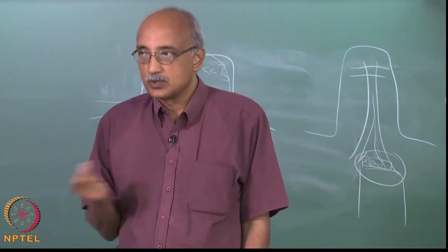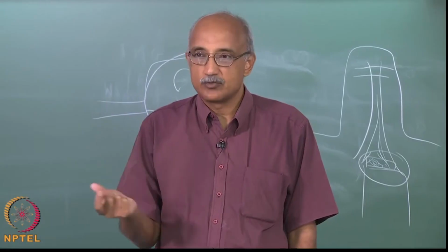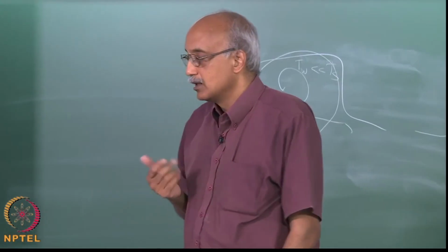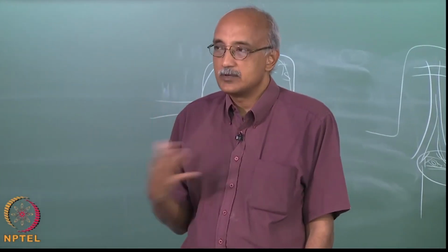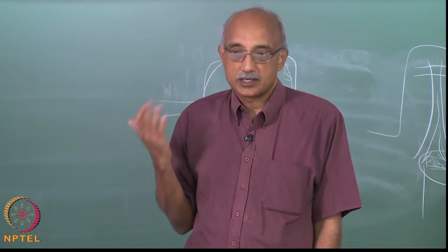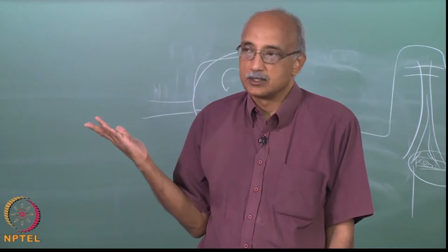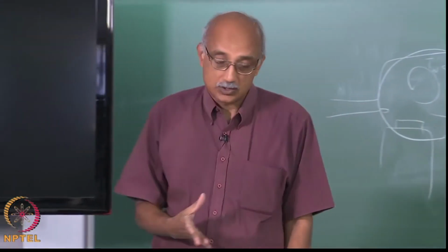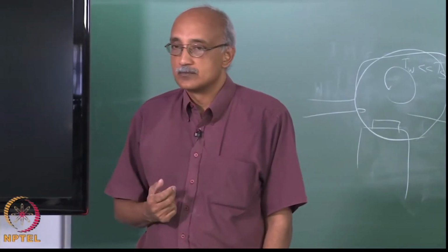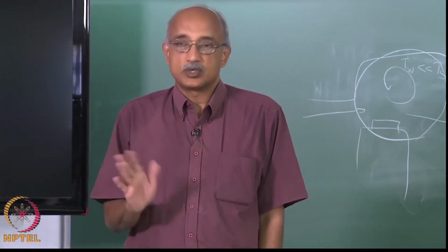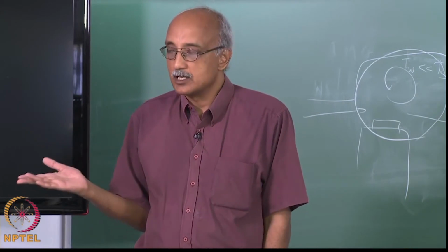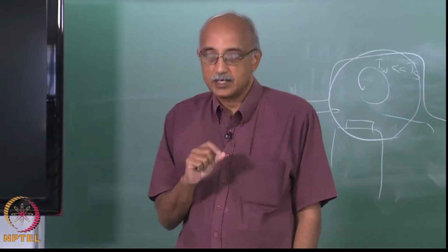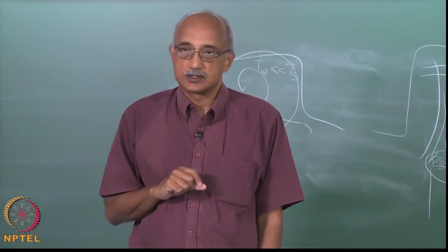And I think it is fair to say that CVD is a process that you invest in only if it is worth it. If you are trying to make a very thick film, or you do not care how good the film is, you just want the film to be there and so on, you are probably better off not even looking at CVD as a process. I mean, CVD is a process that requires chemical engineers to run. Essentially you need chemical engineers to design it, to run it, to control it and to optimize it and so on. Whereas there are many other coating processes that can be done essentially as a turnkey operation, which do not require such a good understanding of what is going on inside the system.